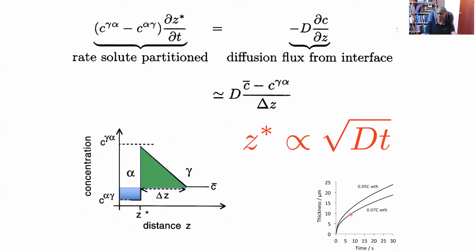And the reason why you get this parabolic curve shape is that as the ferrite grows, the gradient here will become more and more gentle as a greater amount of carbon is partitioned into the austenite. So, straightforward: this is parabolic thickening assuming diffusion-controlled growth.